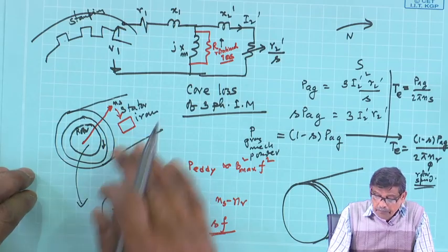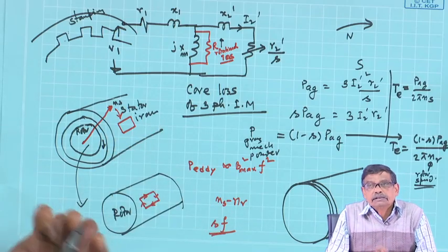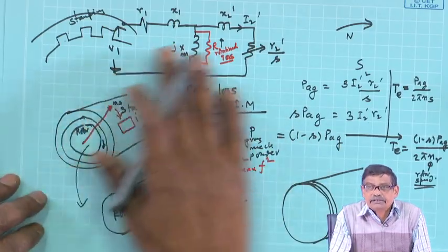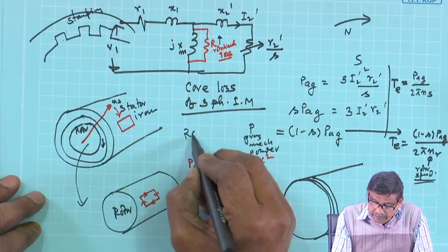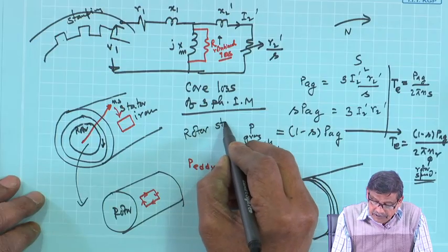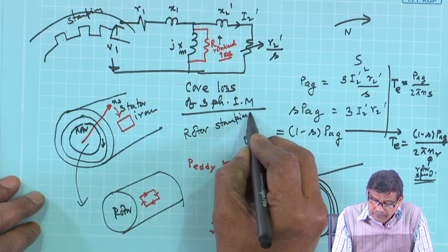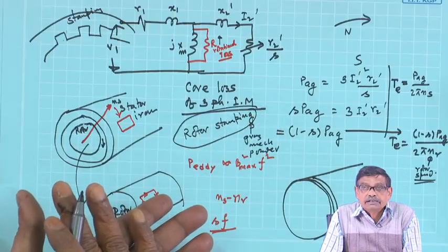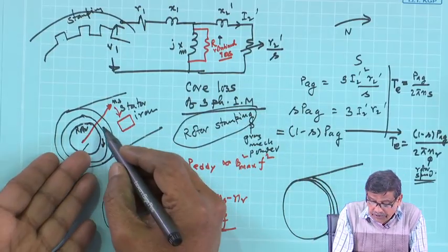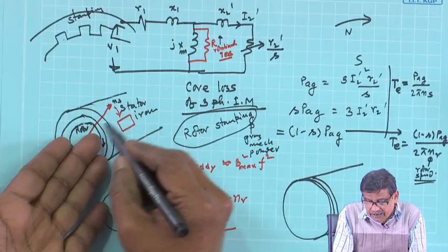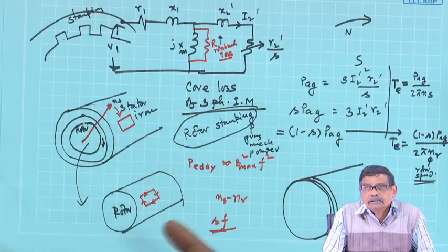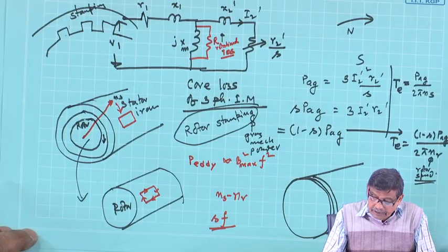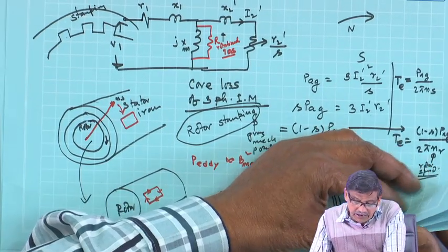Okay, so, always remember circular, thin, short slotted plates are used. Next class I will show you a rotor stamping. Just to point out, a number of rotor stampings are insulated from each other electrically. If you do not insulate them from each other, then eddy current path will remain, they will short circuit. So, that is the thing, okay, we will use that.